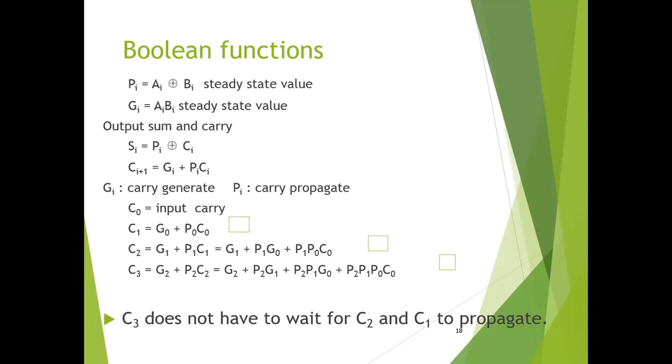An obvious solution for reducing the carry propagation delay time is to employ faster gates with reduced delays. However, physical circuits have a limit to their capability. Another solution suggested is to increase the complexity of the equipment in such a way that the carry delay time is reduced. There are several techniques for reducing the carry propagation time in a parallel adder. The most widely used technique employs the principle of carry look ahead logic.